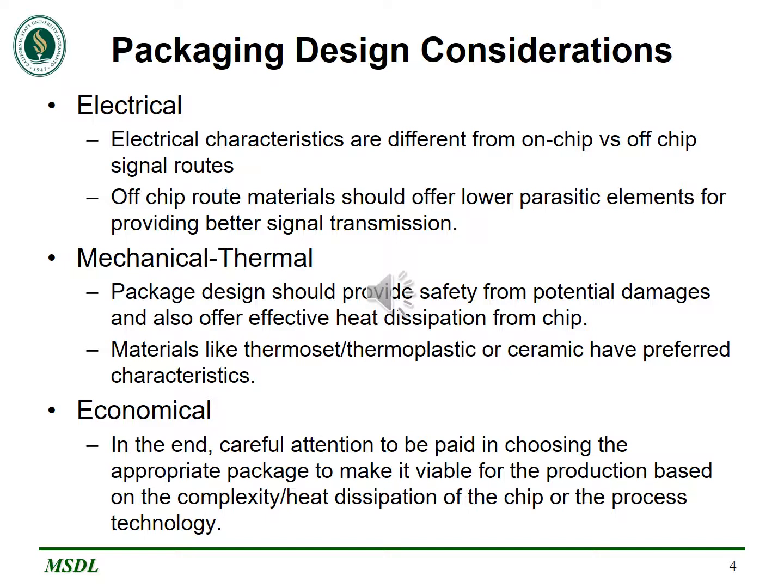We can also consider materials like thermoset, thermoplastic or ceramic, which have the preferred characteristics. Coming to the third one, that is economical. Careful attention should be paid to choosing the appropriate packaging to make it viable for production, considering complexity, heat dissipation of the chip, or the process technology.